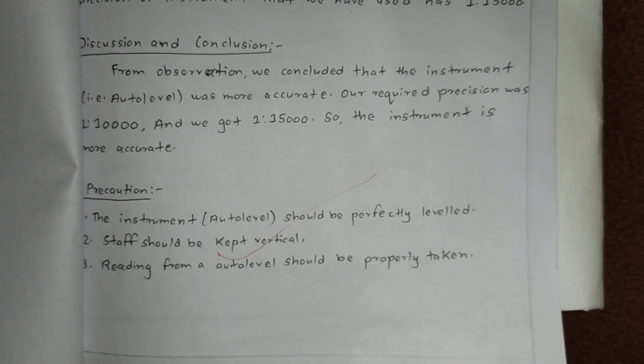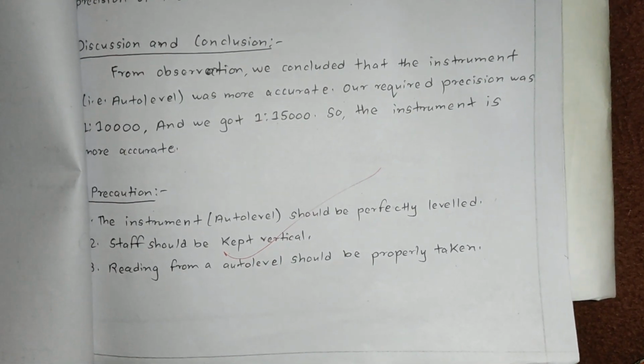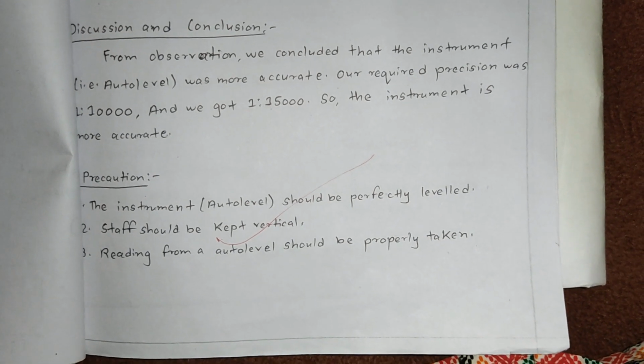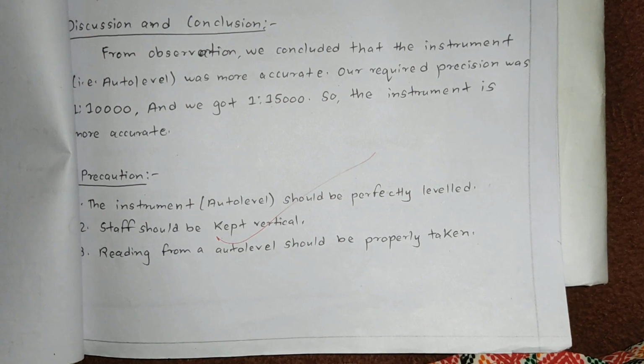Precaution. The instrument, auto level, should be perfectly leveled. The staff should be kept plumb. Readings from the auto level should be properly taken.